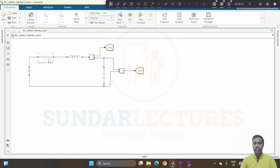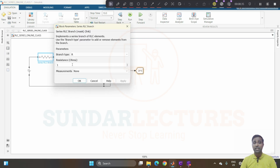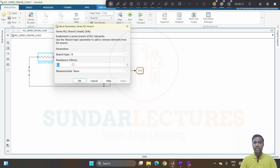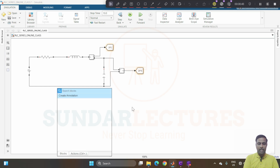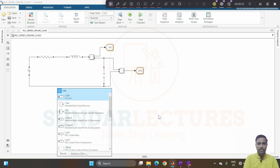Now, what is the value we have given for the resistance in overdamped condition? It is 16 ohms. So I am giving it as 16 ohms. That's all. This is the first circuit that we have created now. And what you do now, you just copy it. Maybe you just double tap here, and then you give it as over damped condition.